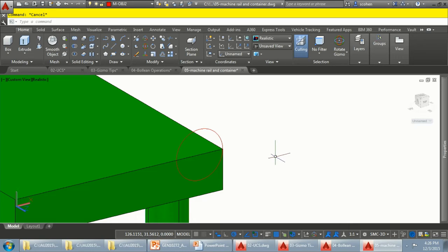Now, when you trim, trimming is definitely something you want to be aware of. If you're trimming stuff in 3D, you have to be on the right plane. When you go to trim, I'm going to use the All option. Here's a little AutoCAD tip. A lot of people don't even realize this is here. If you just press Enter right now, every object becomes a trimming object, or cutting element.